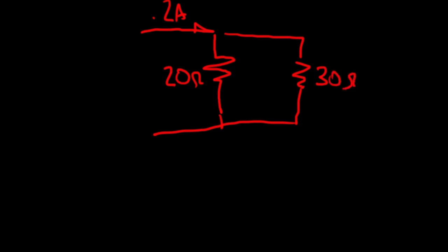Now remember the definition of resistance. Resistance is a force that is inhibiting the flow of electrons. So this has more resistance to the electrons. So I should expect less current in this branch than I get in R2. So when I look at my answer, I always want to check that for reasonableness and say, hey, did R2 have more current going through it?